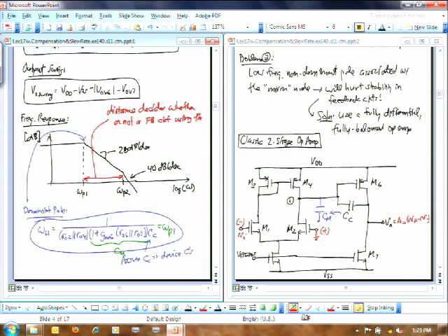That distance makes a big difference. You essentially have to make sure that this distance is big enough. And it depends on what gain you're trying to implement with your feedback. And so I think I'll just leave it at that. You want this distance to be big. And so that's why this compensation capacitor C sub C is here.